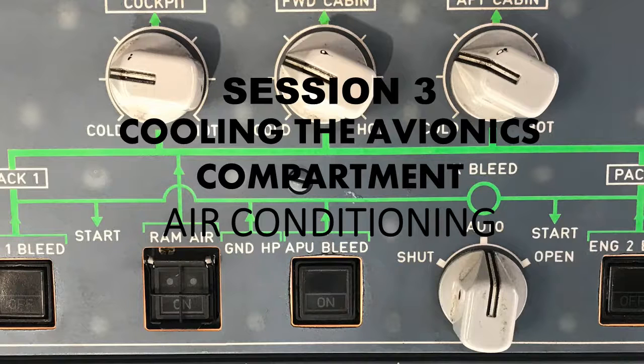The last type of configuration where we can have cooling and ventilation is an open circuit. This is going to take ambient air when the aircraft is on the ground and also when the skin temperature is above 53.6 degrees. That's when it triggers, and now we have ambient air being drawn through the skin air inlet valve, going through the check valve and the filter assembly. The blower fan is going to suck it in through the check valve before cooling the equipment. After going through the equipment, the air is extracted and kicked overboard through the outlet valve. So that's the open circuit situation, and we're dealing with ambient air in that scenario.